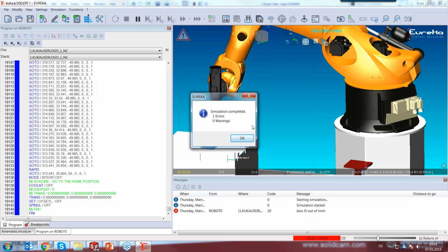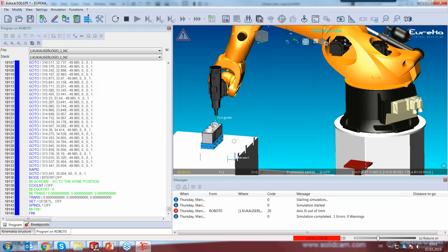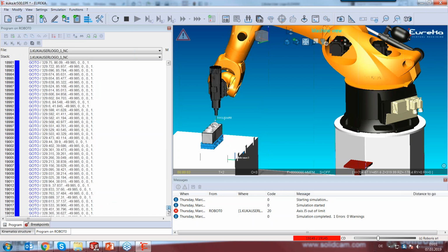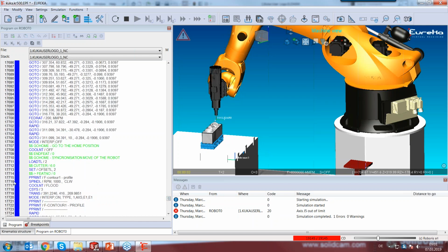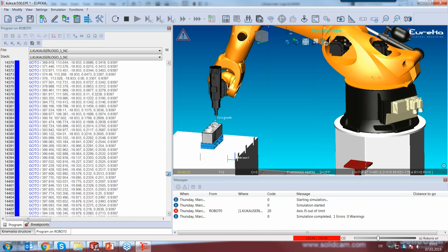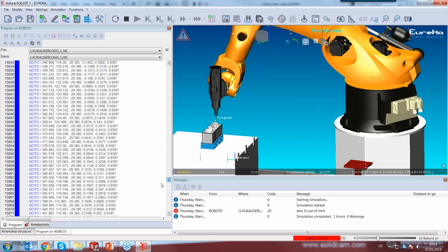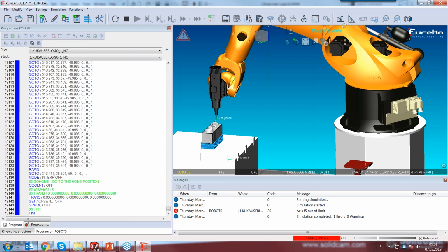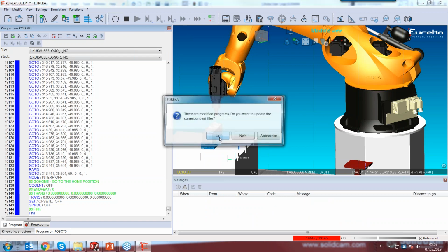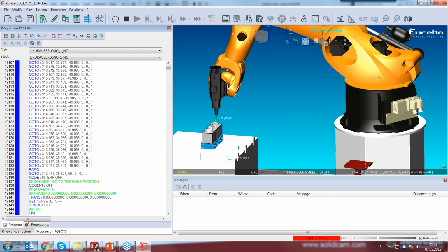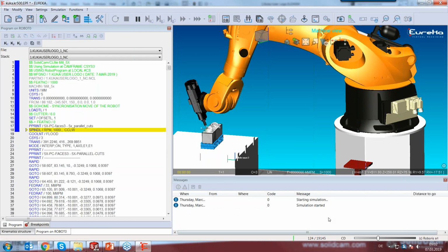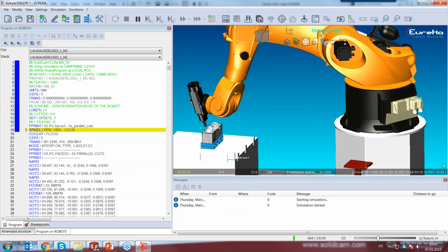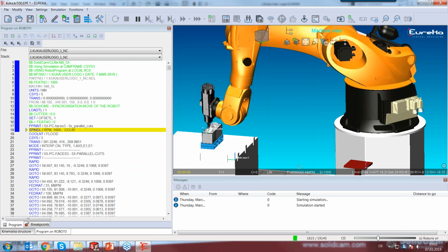Okay, looks good now. Everything is blue. So when in Eureka the toolpath was valid, we see here that everything is blue. There are no different colors. So we are ready to generate now the whole G-code for the program. No, we are not able to do it. Let's do a restart to get aware of the errors we have. First, to see that we have everything in green.